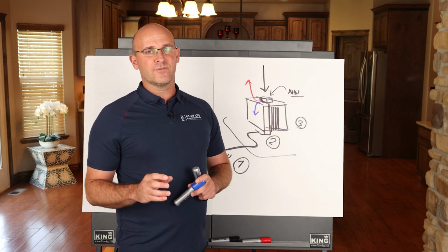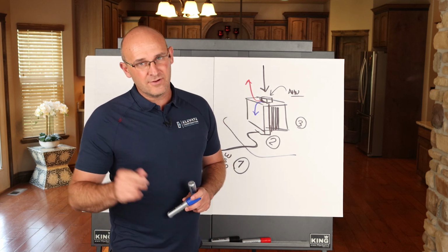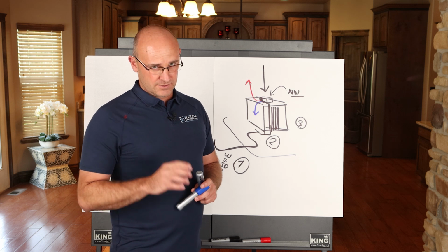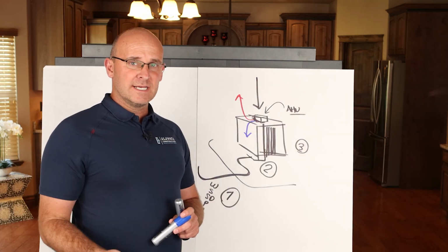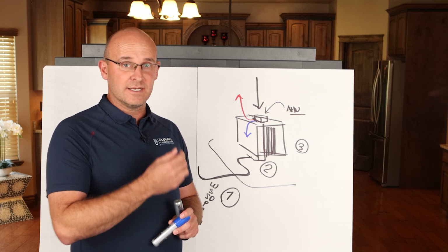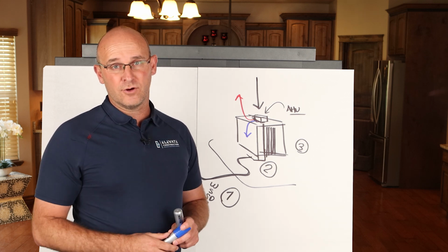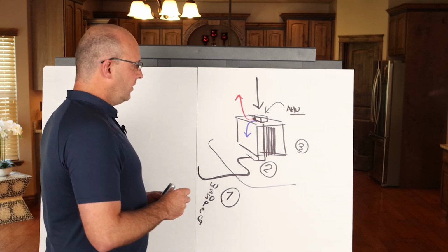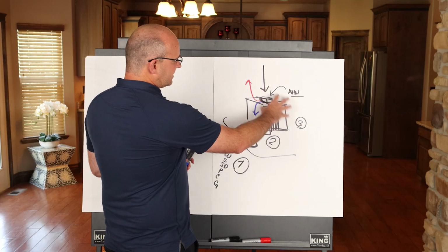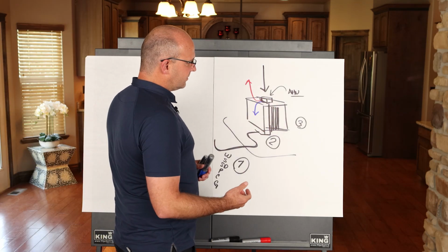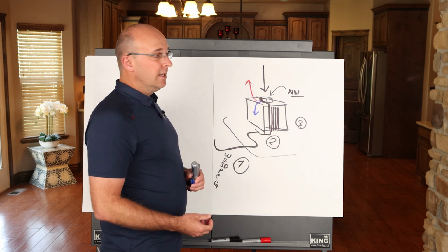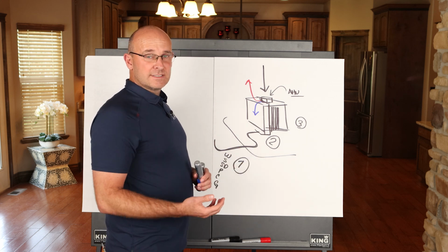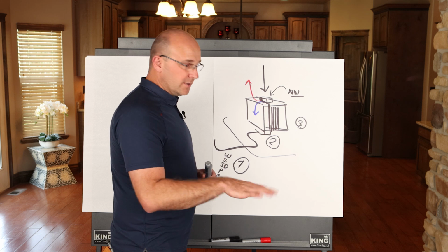If it's not important for temporary conditioning, let's say you've handled that some other way, you'll at least need to have it for your test and balance period. You'll need it for building flush. You'll need it for your overall commissioning activities. So then, once the system is working, you go into your pre-functional checklist, your functional performance testing, right? Your full test and balance, and then the building flush.